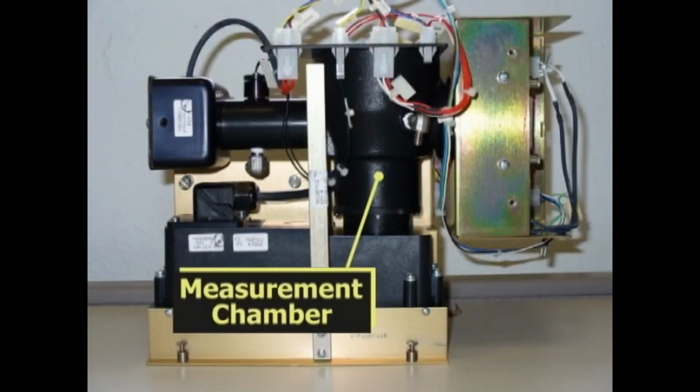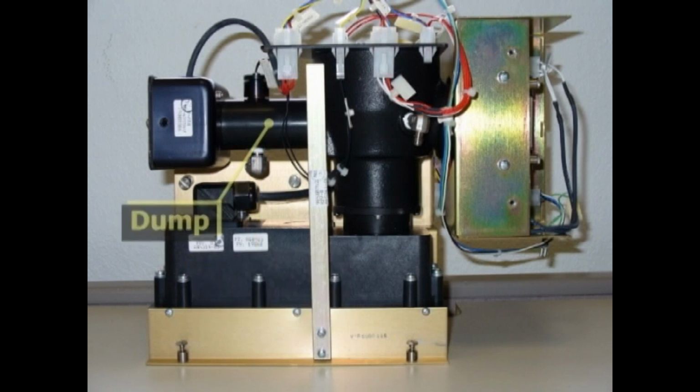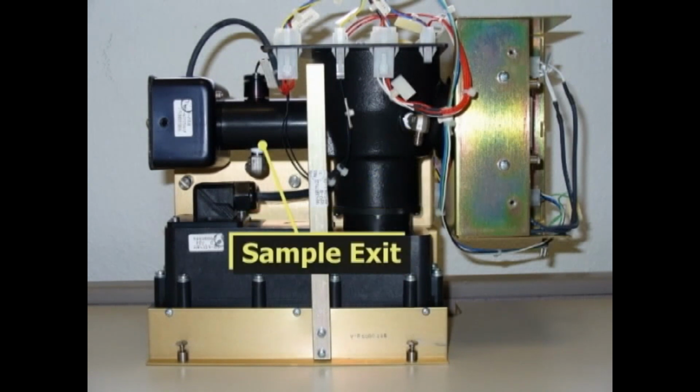The measurement chamber is pneumatically sealed and is where the fluorescence of SO2 actually takes place. The optic test lamp is used to simulate the light that would otherwise be present during SO2 fluorescence and is a very useful diagnostic device. It is mounted on a tube called the dump. The sample inlet is the steel fitting on top of the measurement chamber, and the outlet is the steel fitting on the dump.